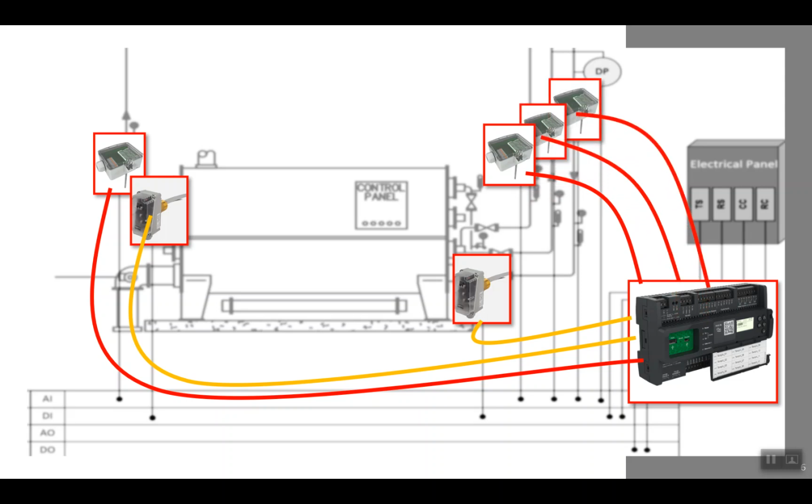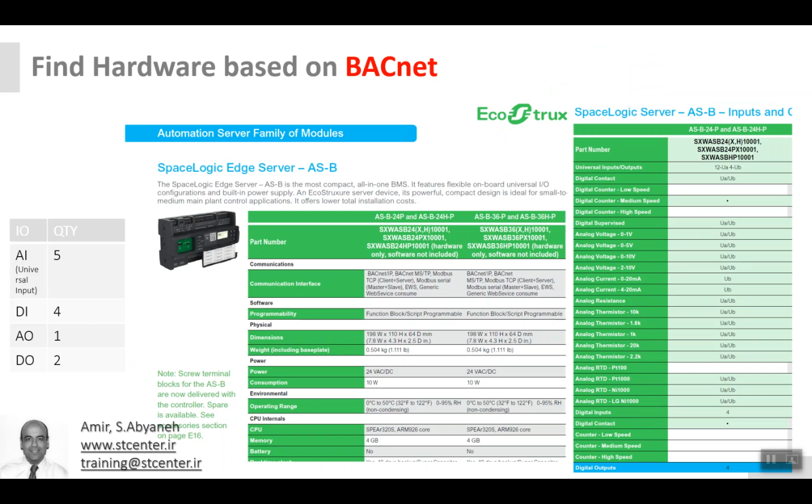We need temperature sensors for input and output of the condenser, and the differential pressure transmitter between input and output of the condenser. Also we have the input and output communication between the main controller input output card and electrical panel.